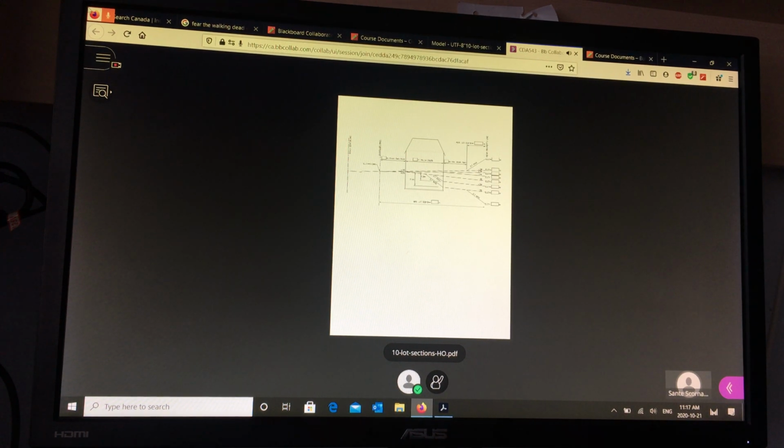Then what we look at is the front of the lot, where the road is, and the back, at the limit of the subdivision. So that's the front, that's the back. In assignment 3, you're going to have an elevation at the front and an elevation at the back. Okay? What you do in between is spelled out in this cross section. So I'm going to assume an elevation here at the front. Let's say this is elevation 0.